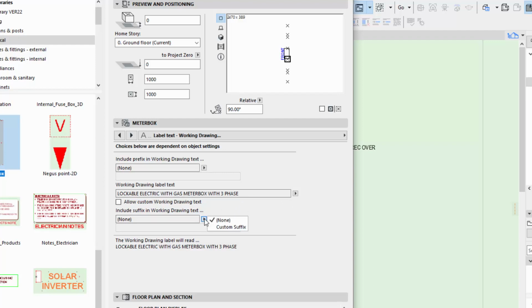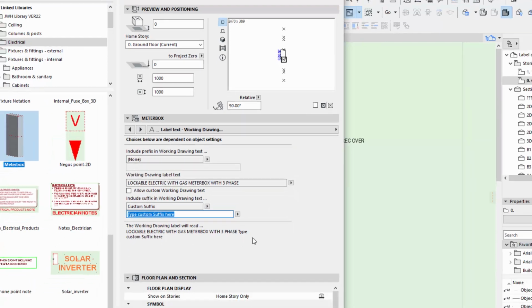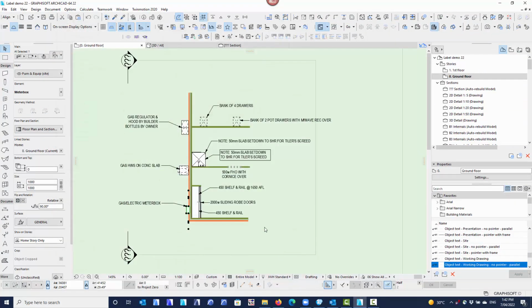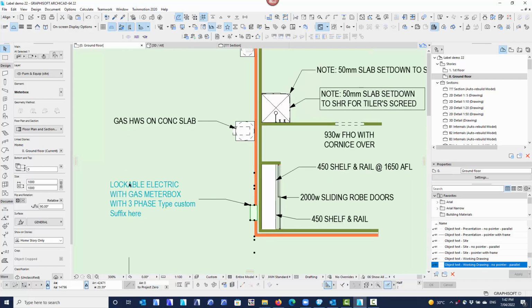You'll also find when you do custom text, so if I was to type something custom in here, I'll just leave that on if you like. When I go to my note, you'll see that it will go blue. So if it's not associated, it goes purple, but if it goes blue, you know that that is not standard information. It's got some sort of custom text in it.